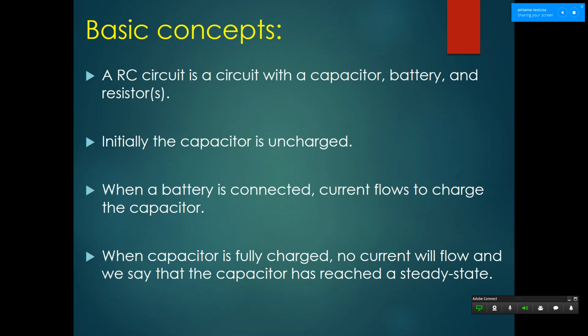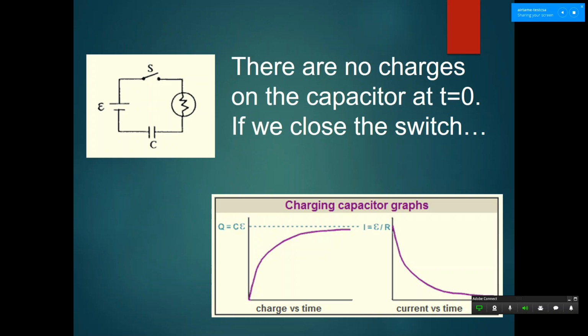Okay, here we are. So here is actually the most simple form of RC circuit. So it's got a voltage source, right? It's got a capacitor, it's got a resistor, in this case it's a light bulb, right? And it's got a switch, all right? The switch is important for this because that determines when we start our timer. This would definitely be found in the camera, yeah. Actually, all capacitors in reality are wired with resistance.